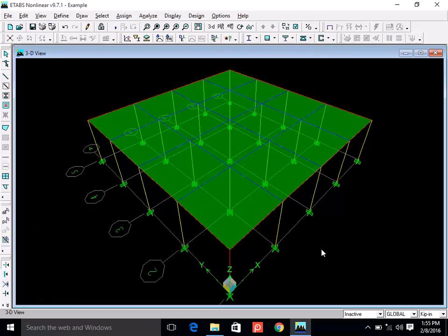Okay. Maybe let's do it wrong, and then we learn that if you do it wrong, what's the problem? And then we correct it and see how it goes. Right now, I have not done meshing. My slabs are like solid surface, okay, no nodes in between. So we'll see what happens. Okay, I will go to analysis. Let me save it first.